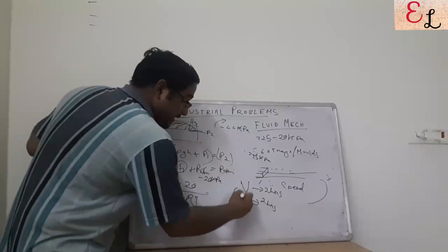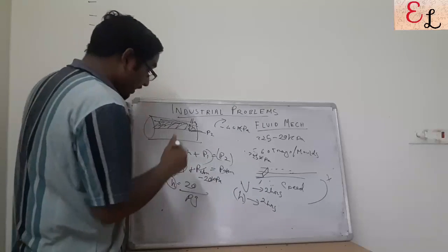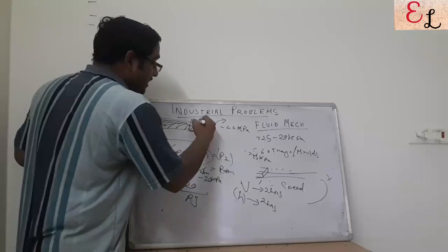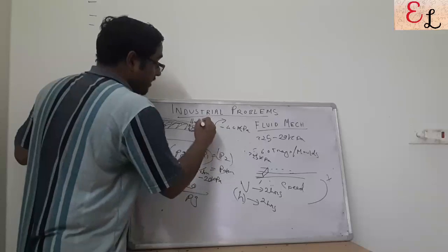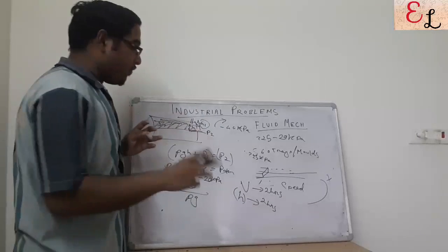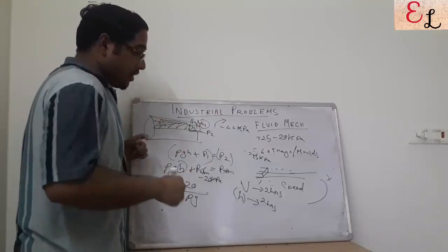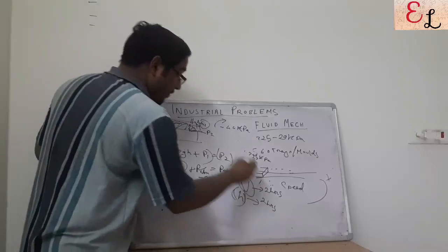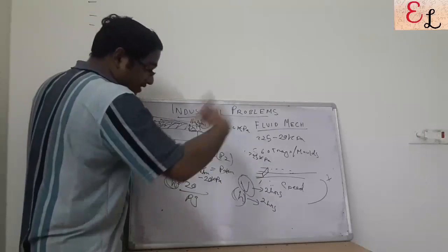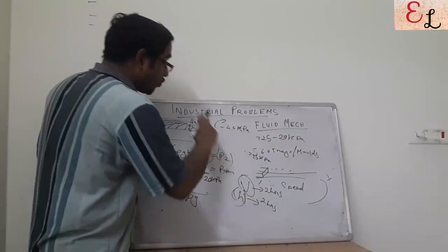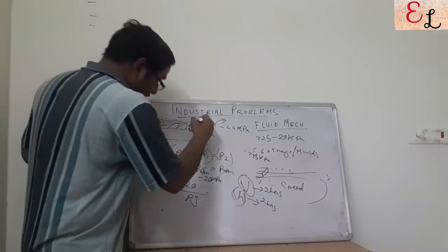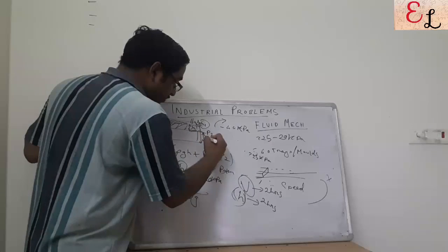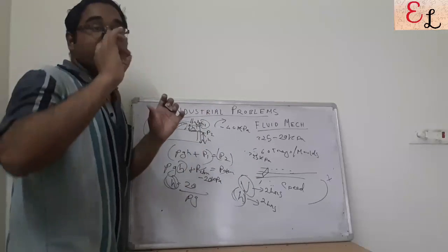And that height will correspond to the height that was initially there above the bed plus the extra height due to slag bed formation in those 2 hours. So that's going to give me the total height. The total volume will be this volume plus the volume that is formed. That will correspond to the total height of the bed from the base, minus the slag tapping hole height, which will give you the height of the bed above the slag tapping hole.